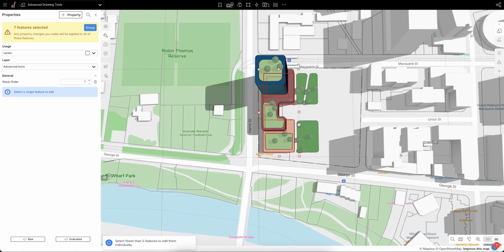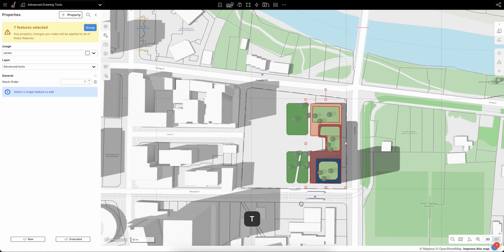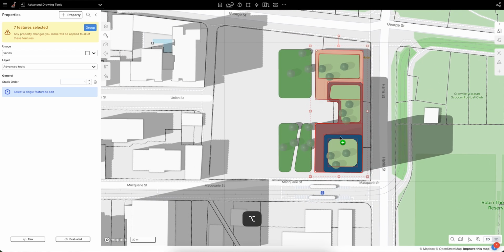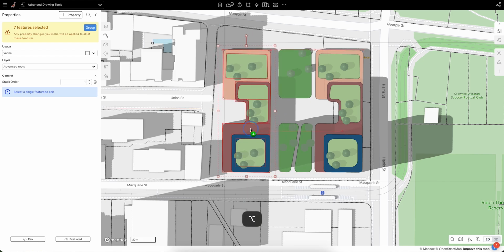And what I want to do is I first want to copy this geometry, because when I mirror it, it will mirror it without a copy. So I'm going to toggle into 2D mode actually. I'm going to hold Option or Alt on my keyboard and just drag this copy across like that. So I'm happy with that positioning there. And now I want to mirror that and flip it over so it's the inverse, and we've got these indents facing each other.